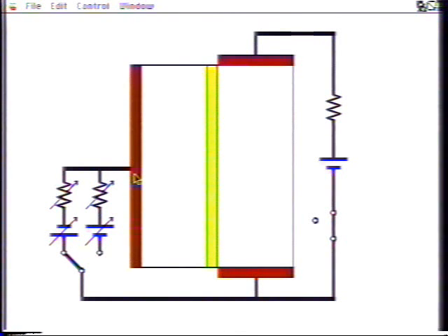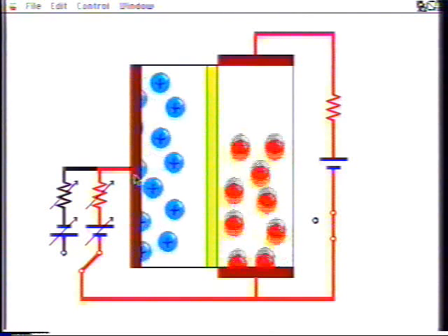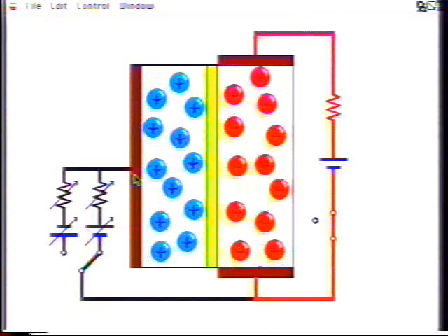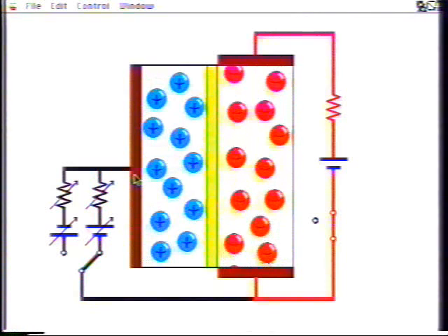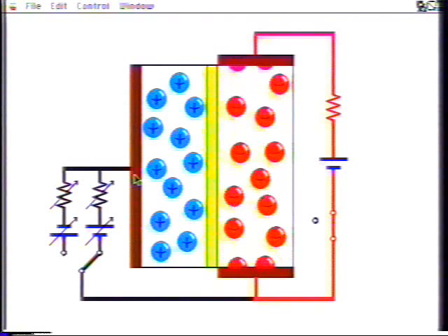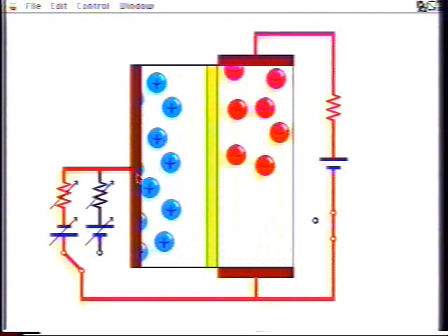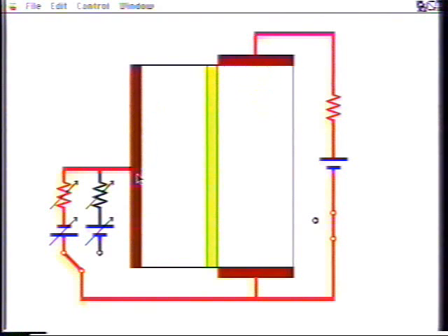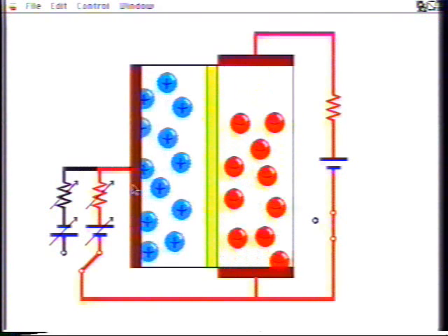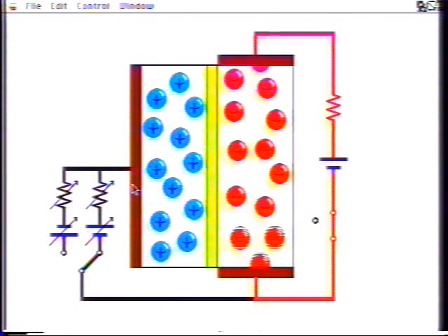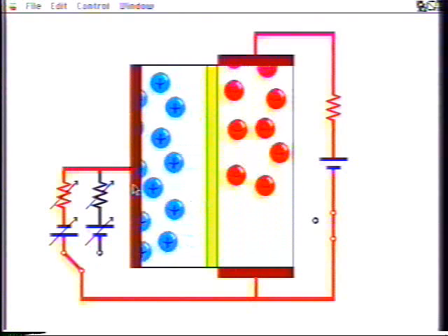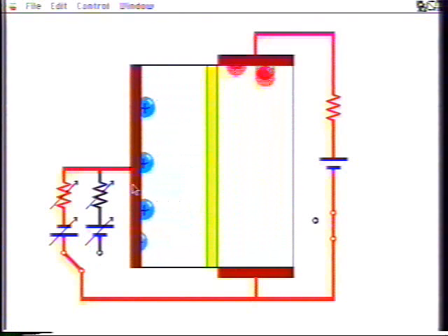Here's another repeat of the off-on-off sequence with a larger amount of gate control charge. The transient charging gate current is increased, and so is the number of electrons available to carry output current. The transient discharging gate current is also increased. It's obvious that there's a speed concern to do with closing and opening the switch. The drain current does not start and stop instantaneously.